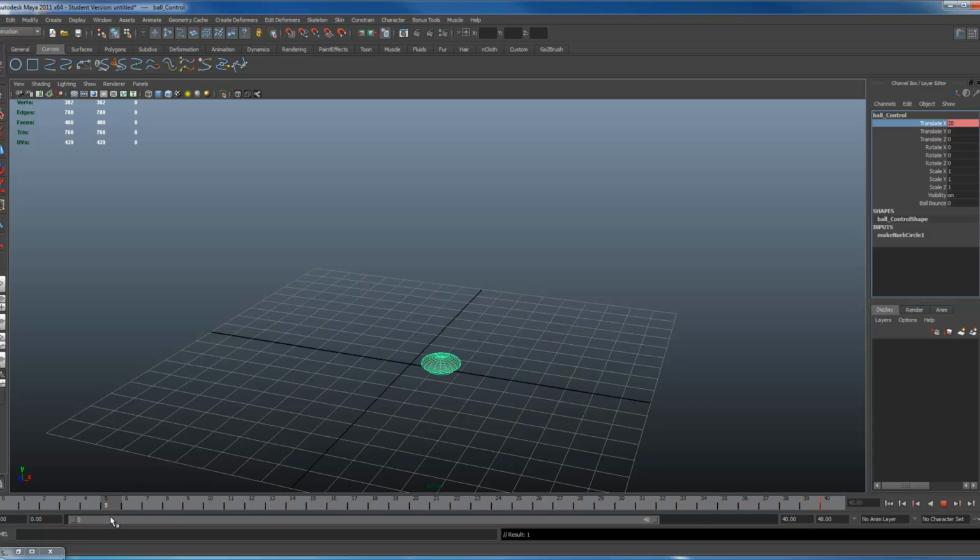Lands. So in these little frame intervals, we'll have to have them inside. So at 10, actually let's go back here. I'm going to key 0, key selected. Frame 10. Because this has to bounce in midair. See how this goes, what speed this goes. And that sounds like a good bounce.